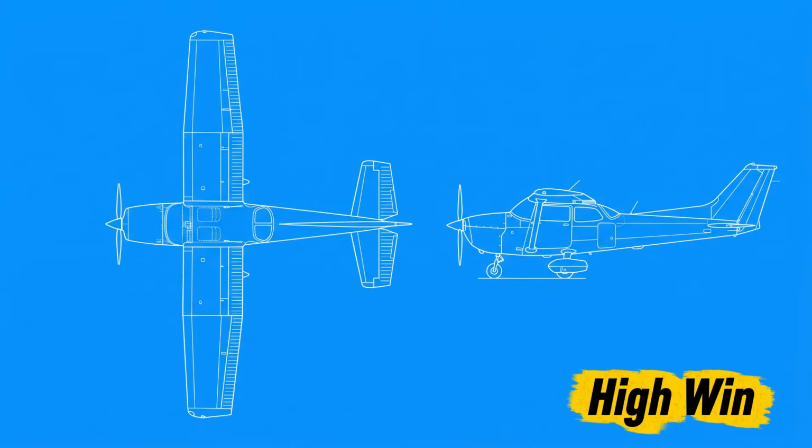The high wing is mounted above the fuselage, giving the aircraft strong stability and a clear view below the wing. This arrangement is useful for transport, utility and observation aircraft, especially on rough surfaces, but it can add structural complexity and may produce more interference around the fuselage and wing roots, and it suits utility aircraft.